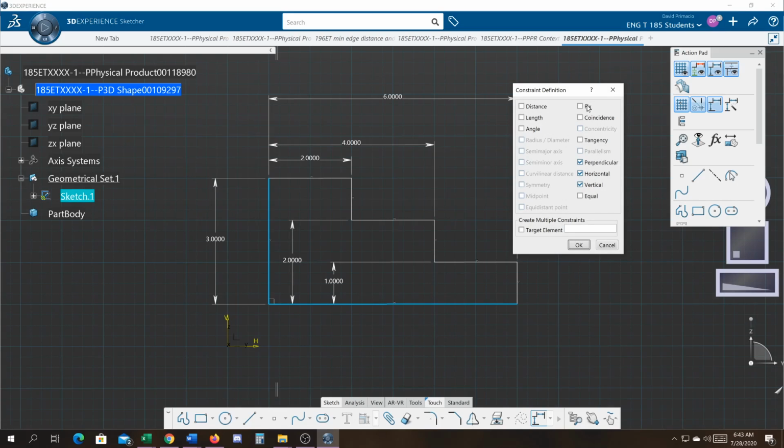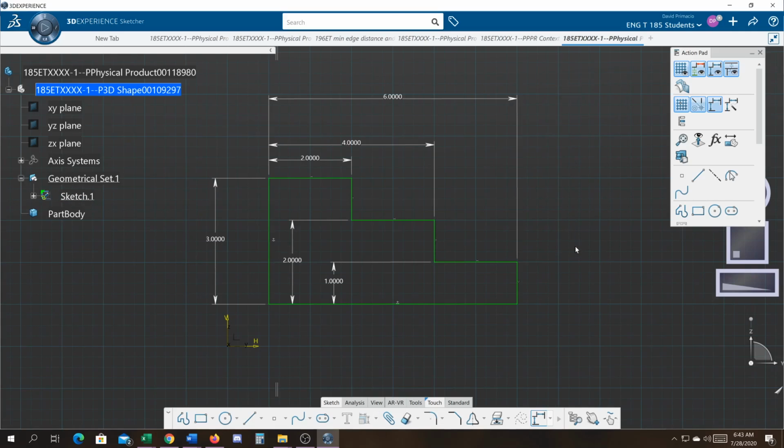We're going to apply the datums by hitting fix. Remember, in CATIA, datums are fixed, anchor, or reference elements. I'll turn off horizontal, perpendicular, and vertical. If you do not turn those off, it will not go through a check process through EDC, Engineering Data Control. It will recognize that as double dimensioning. It will be red H's and V's or black H's and V's, letting you know, hey, I'm a datum. I don't need to be horizontal and vertical because I've already established that I'm the datum and the horizontal and vertical are no longer relevant. I select OK. The part is green.